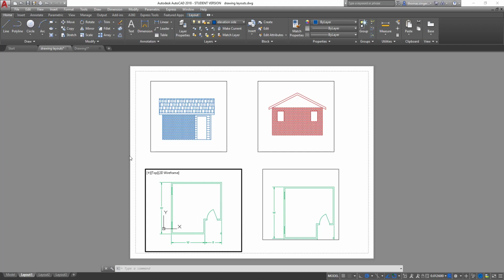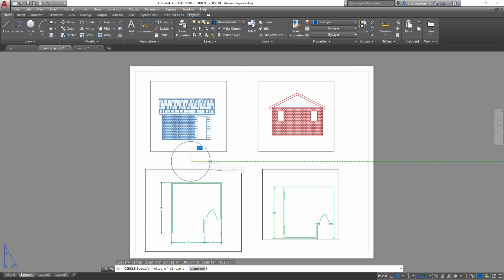So in this case, when we double click out, we're actually working on top of the drawing sheet. So that 8.5 by 11 sheet of paper that we were working on, we're literally drawing on top of that drawing sheet. Again, let me give you an example. Notice that the circle is covering the viewport boxes. If I work inside here, remember we created a circle inside, it dynamically changed or updated. If that was the case, I should see a portion of the circle inside here, and I don't. So when we're outside of the layout, we're actually drawing on top of the piece of paper.